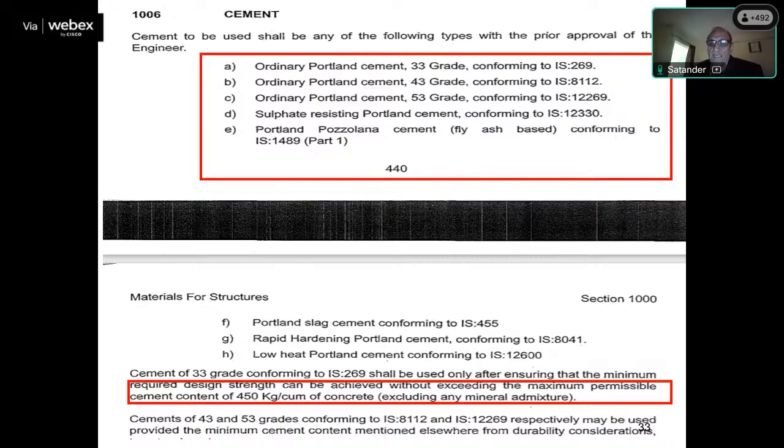The most important part is maximum cement. Setting of curd and setting of cement are the same. If you are preparing curd, you take toned milk, not fat milk. Too much here also: if cement is more than 450, you will not get good concrete. You can use fly ash or slag or anything. Maximum cement is 450 kg per cubic meter. It means in 2400 kg total material, your cement should not be more than 17 or 18%. Correct?